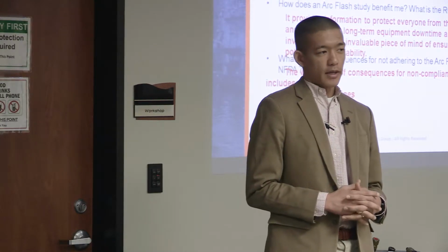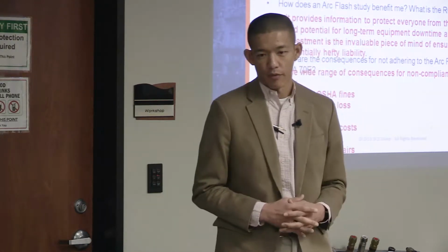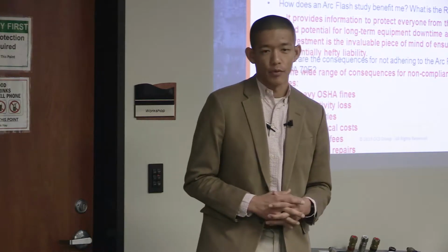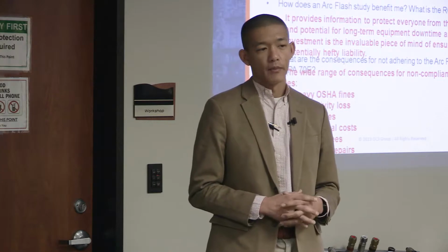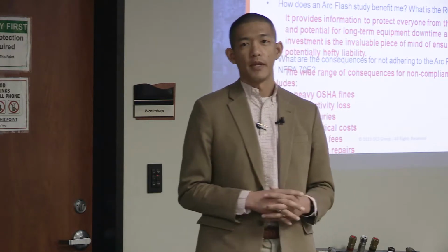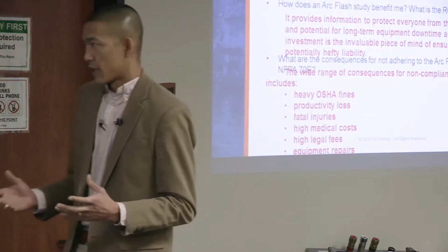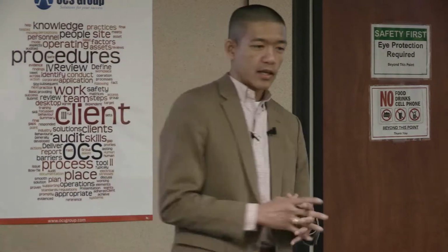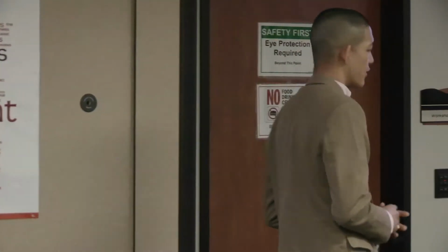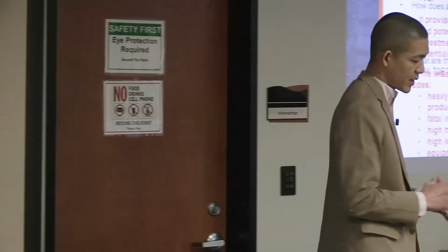All the clothing that you purchase for working on live electrical equipment is now rated in calories per centimeter squared, but the models that were used inside of the standards were always based on joules. So that's one thing that you do need to take note of, and the units of measure are actually quite